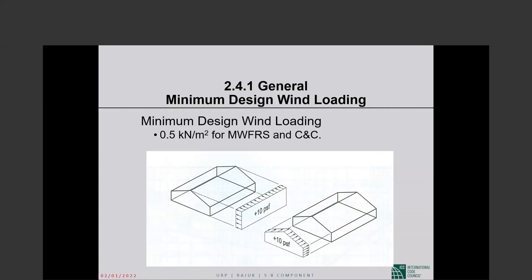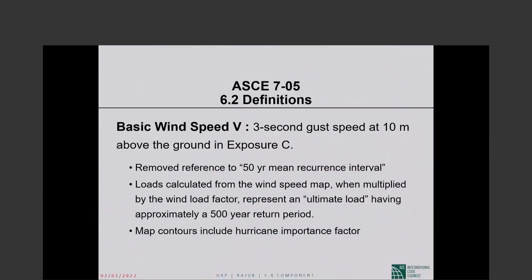Now, we have a pressure distribution that we have calculated. We are not saying if you calculate values less than 10 pounds per square foot, make it equal to 10 pounds per square foot. No, you don't tamper with what you have calculated. You design your building for that distribution and also this distribution. This is like an additional load case. That is quite important.